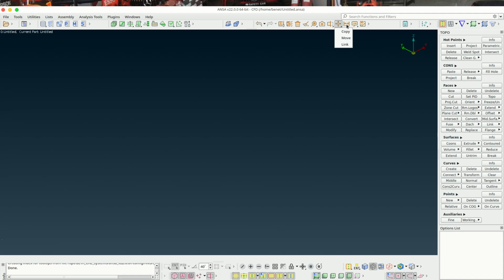When I say check, it's because Ansa is quite a complex program, as most preprocessors. So if we have some function activated that we don't know is activated, or we are not aware, basically the mesh is not going to have the size that we want. So it's important that after meshing we just double check at a couple of points that we have the correct length.